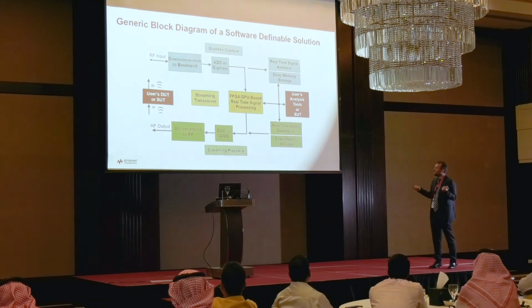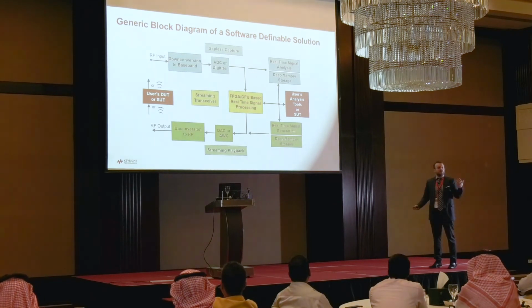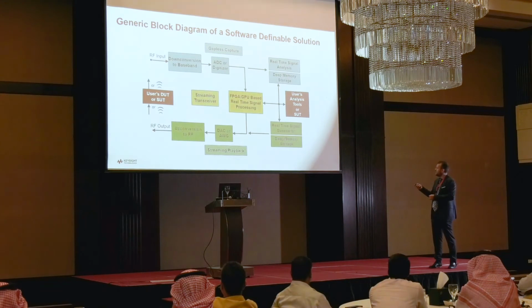One of those things is we could do a very fast feedback. So we have capabilities for feeding that high-speed, wideband, high-resolution data to an FPGA to perform processing, much like we're doing with the PXI modules. And we can feed that to our AWG and upconvert it directly. We can also do deep storage.